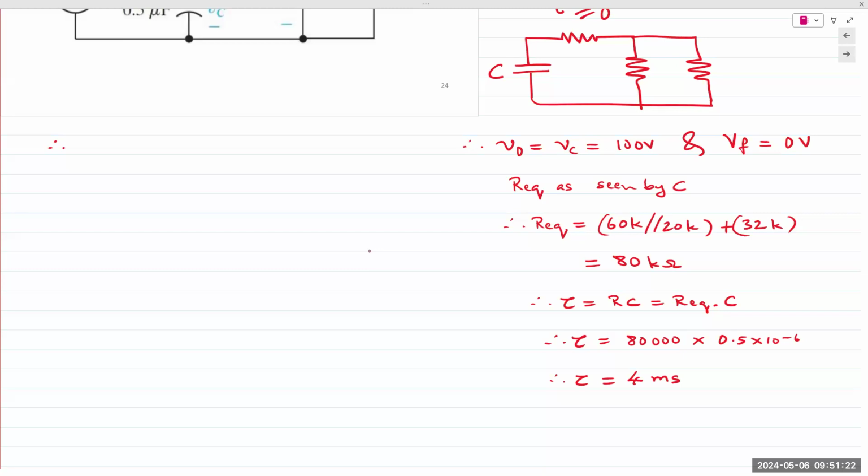Yes. Yeah, the capacitor acts like an open circuit, but after t equal to 0, when the switch is flipped, we are no longer concerned with that resistor. Anything that's on the left side of the circuit is disconnected. So it doesn't matter what resistors are connected. There could be 100 resistors and we wouldn't care. Yeah. All right. Does that make sense? Yes.